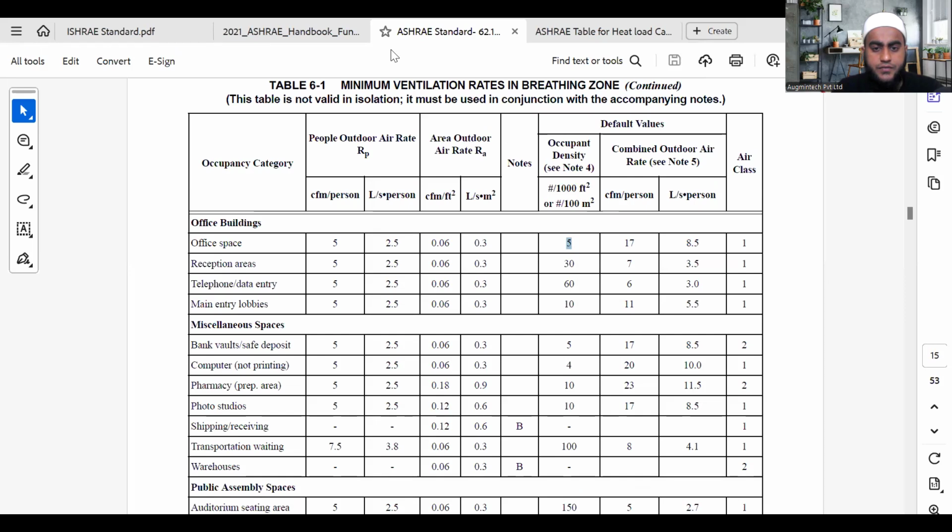Where we have considered full height instead of 12 feet. Yes, tell me, for exposure wall you're talking about. Where do you have confusion? See, for exposure wall, we have to consider the wall which is exposing to the sun. The heat will enter from outside to inside through the complete wall, na? So we have to consider the complete wall only. Okay?